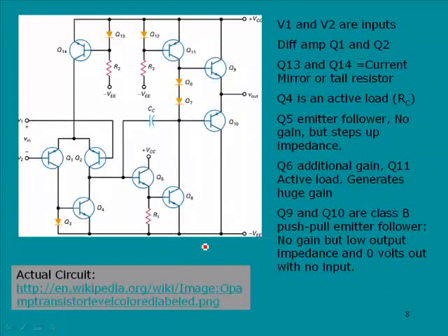This is a simplified schematic diagram of what we just looked at, and this makes it a little easier to comprehend. Remember, this would be that resistor that controls the current into the differential amplifier. These are the inverting and non-inverting inputs coming into the differential amp, and then the output is fed over here. You may recognize this. This looks like the Darlington pair that we looked at in transistor circuits. And in this case, I should mention this also. Here we have a resistor controlling current.